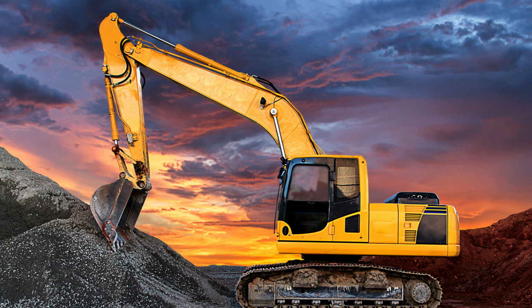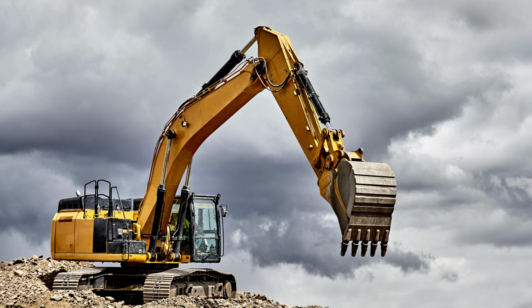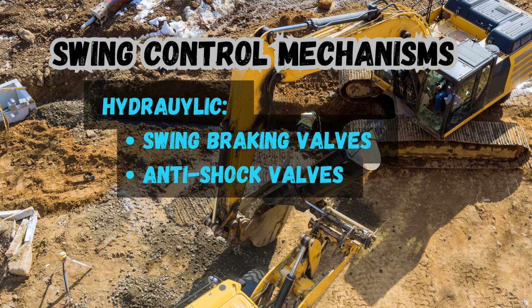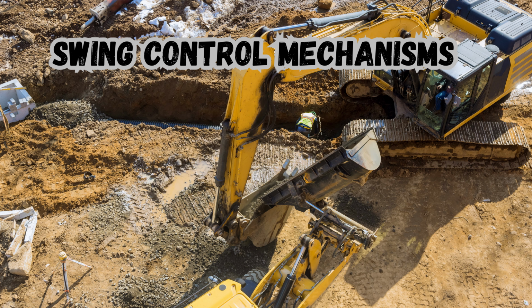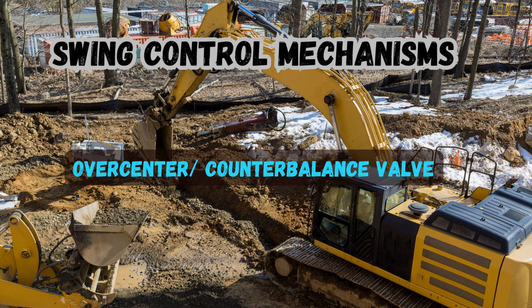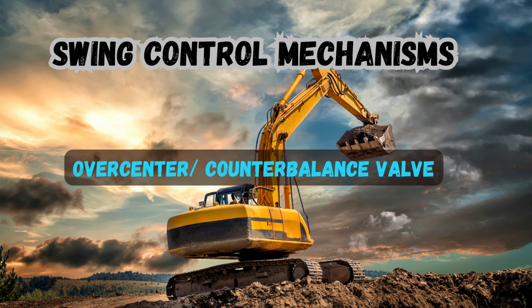To control these dynamic effects, modern excavators incorporate several swing control mechanisms. Hydraulic systems include swing braking valves and anti-shock valves that regulate the flow of hydraulic oil to the swing motor, allowing the rotation to accelerate and decelerate gradually. Hydraulic cushioning is also used to absorb sudden pressure changes within the swing circuit.